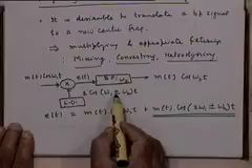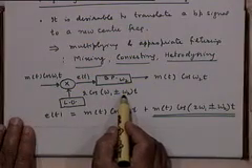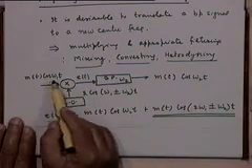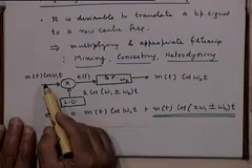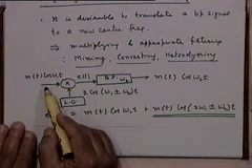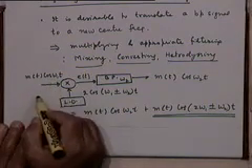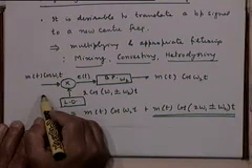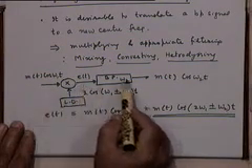Now there is a very common problem that one encounters in this process, right? It's a common problem in all mixers of this kind. Suppose you take ω1 plus ω2 here, right? And let's say at the input, along with this signal, I also have a signal at frequency ω1 plus 2ω2. Okay, so along with this I have another signal which is centered around ω1 plus 2ω2. Now what will be the output of this system?